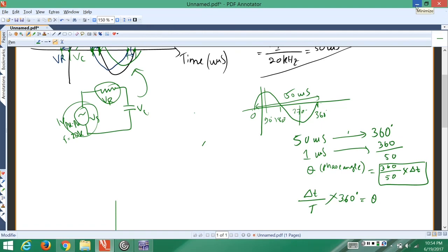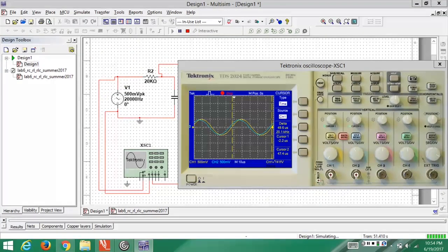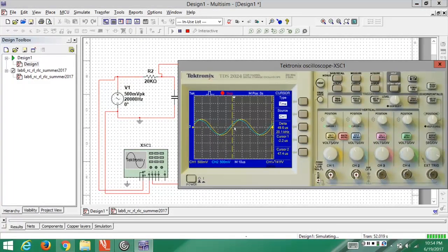So if I go back now, I need to find del t from this waveform. When I am on the channel yellow waveform, that is channel 1, let's use one of these differences over here. Let's select the cursor again, and let's move it.